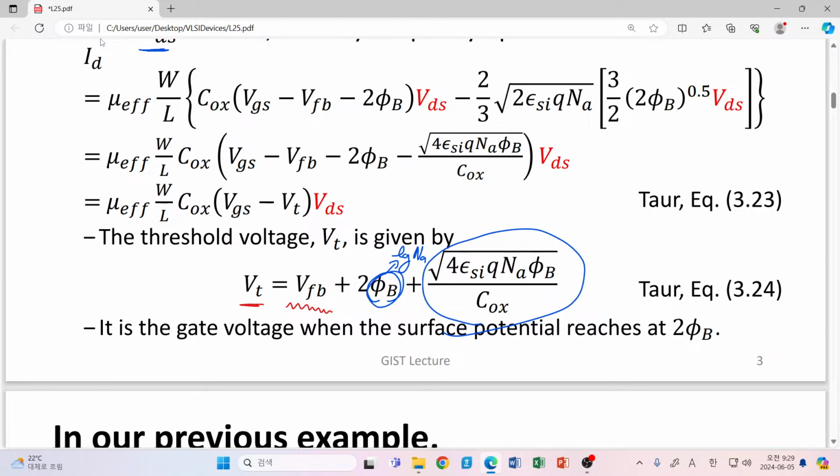If we can increase or decrease this flat band voltage anyway, then depending on our change of flat band voltage, we can also directly control threshold voltage. Wow, that is the best way we can do. But at former times, why have we not tried it this way? At the time, due to the limitation of our technology, previously we did not actually use this metal gate.